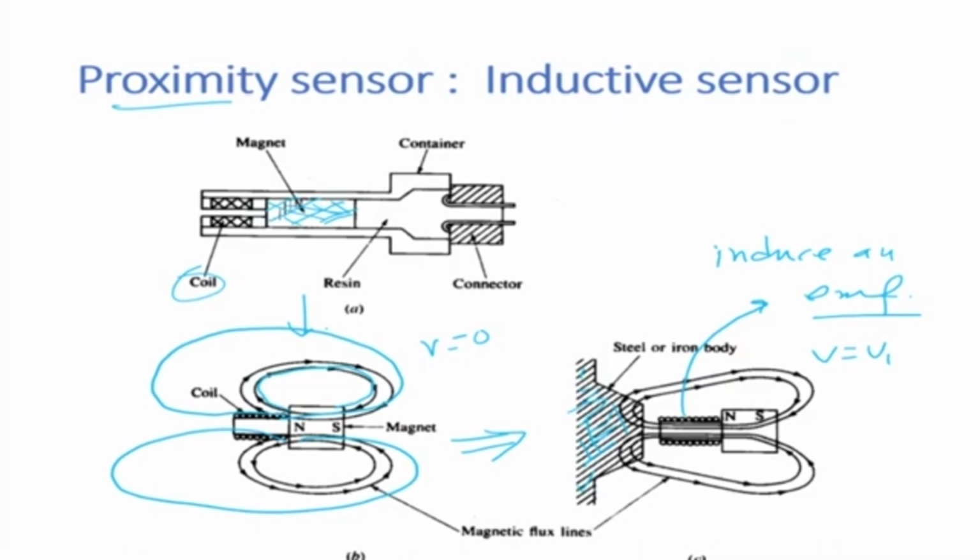For example, when we come to applications of robotics, if you look at what the robot is applied for in industry, it is for pick and place applications, spot welding, spray painting. So on the conveyor, say a part has come, you have to sense that the part has come. How would you sense that? An inductive sensor can be put here like this. The moment the part has come, the inductive sensor senses it and tells the robot that the part has come. Now you can go and pick it up. So this is the application of inductive sensors.